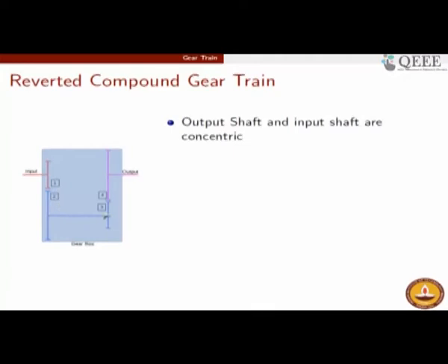But gear 3 moves at the same angular velocity as gear 2, because both of them are mounted on the same shaft. The angular velocity of gear 2 is given by the ratio of size between gear 1 and gear 2. Once you find the angular velocity of gear 2, you can find that of gear 3 to be the same.